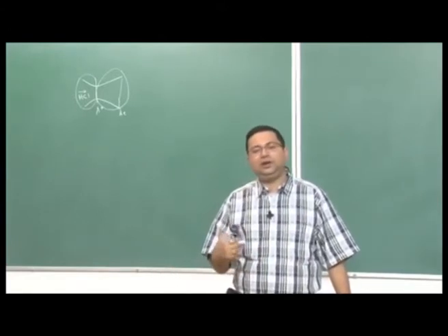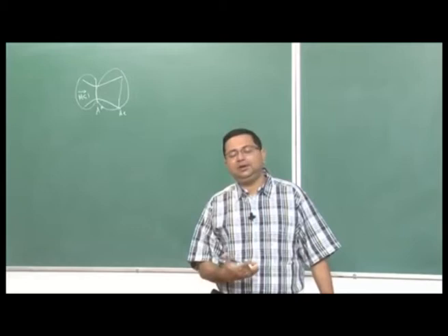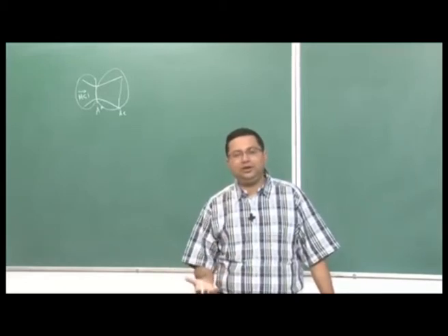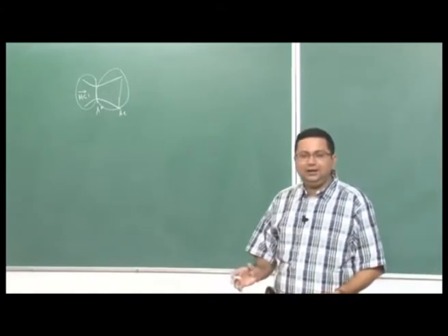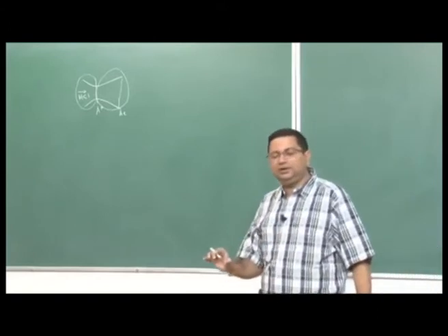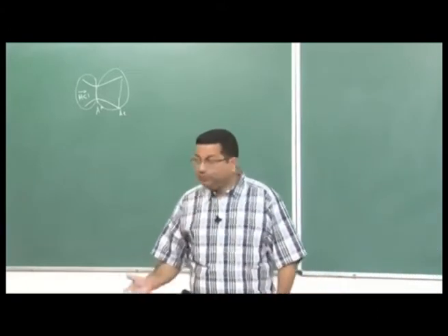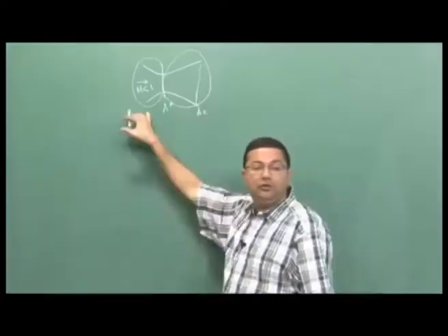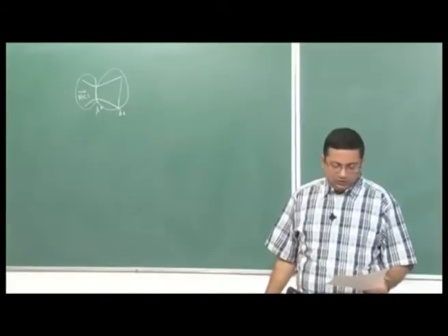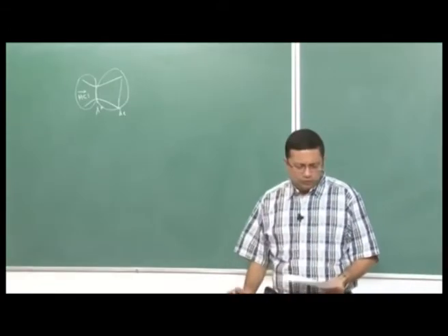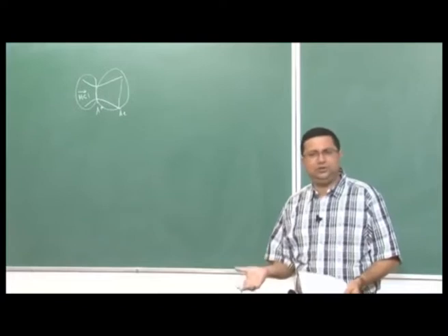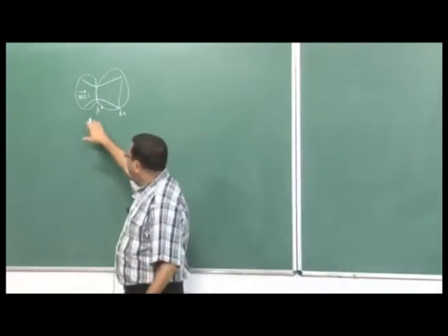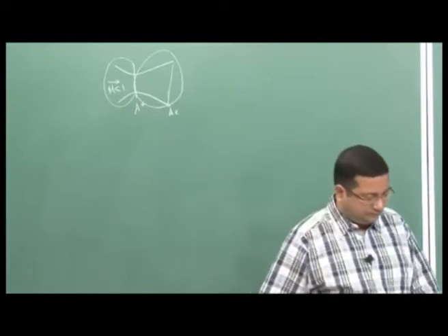It is just a subsonic flow in the converging passage, and since the passage is converging, there is no possibility of flow separation or anything. So, we can choose a design with a simple geometric convergence that will be good enough for us, because here we have a favorable pressure gradient. The pressure is decreasing in the flow direction. Therefore, a reasonably smooth contour provides pretty good subsonic flow. There is no question of separation, and losses are also not very high. So, this side is not of much importance.